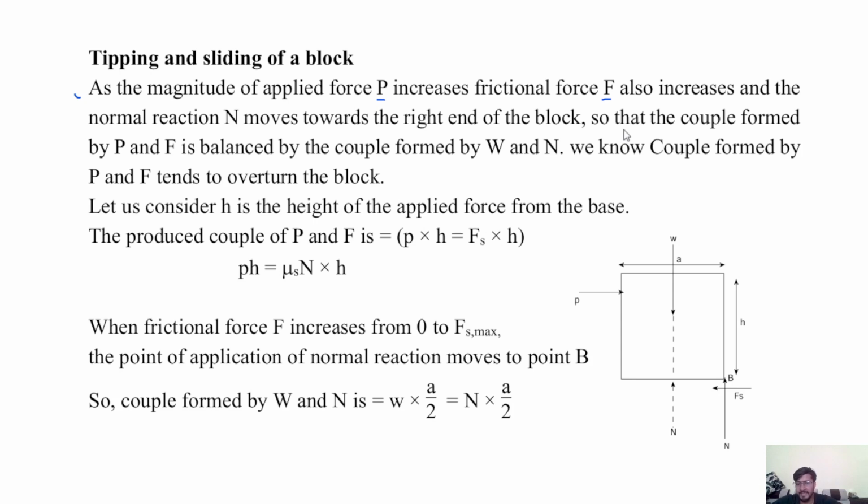So P increases, frictional force F also increases, and the normal reaction N moves towards the right end of the block.